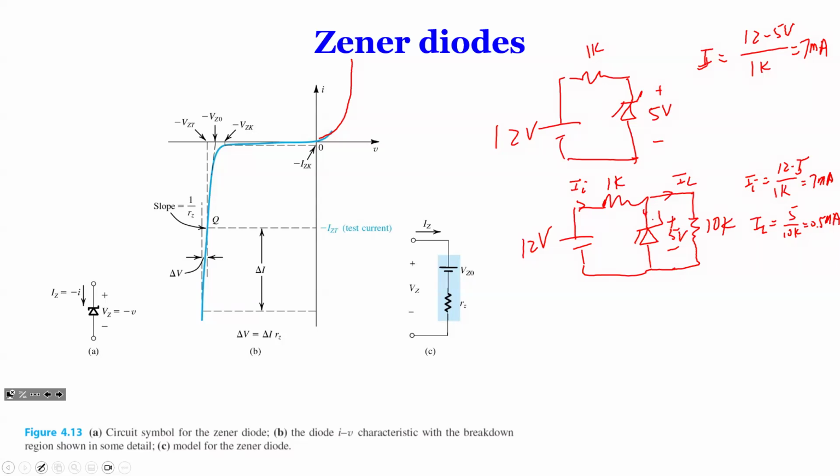So you can calculate Zener diode current. That's called IZ. It's going to be II minus IL. That gives you 6.5 milliamps. So your load draws some current. Initially the current in the Zener diode is 7 milliamps because everything flows in a circle. Now, because the load gets 0.5 milliamps, the total current in the Zener diode is reduced by 0.5. You have only 6.5.